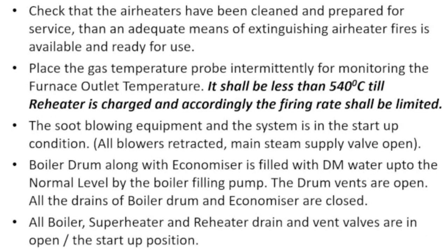Check that the air heaters have been cleaned and prepared for service, and that an adequate means of extinguishing air heater fires is available and ready for use. Place the gas temperature probe intermittently for monitoring the furnace outlet temperature. It shall be less than 540 degrees centigrade till the reheater is charged, and accordingly the firing rate shall be limited.